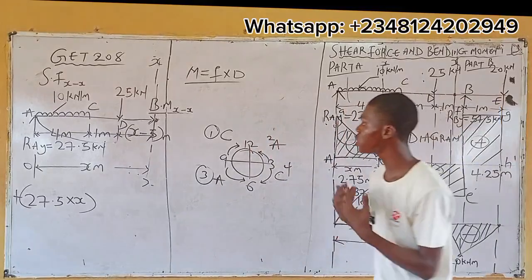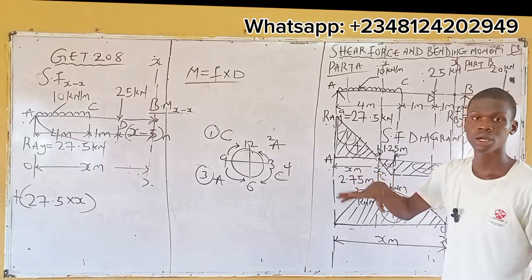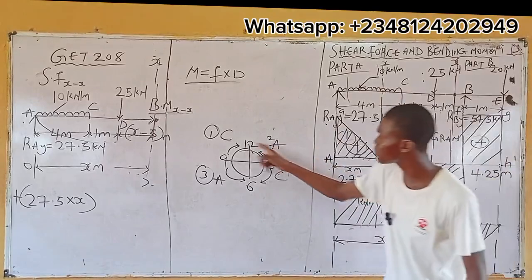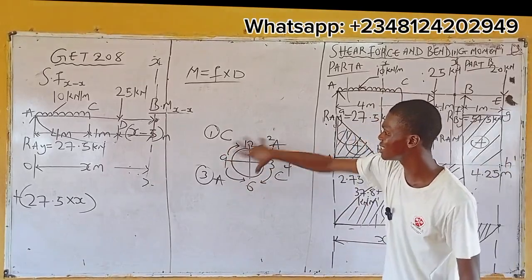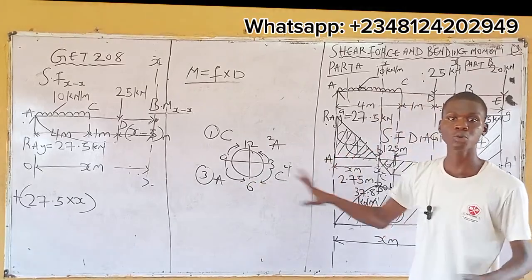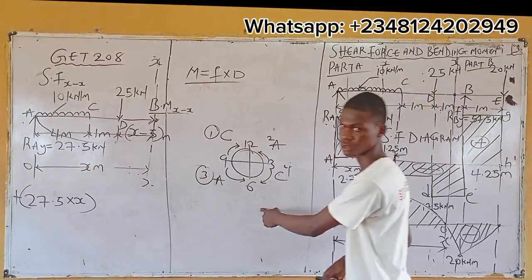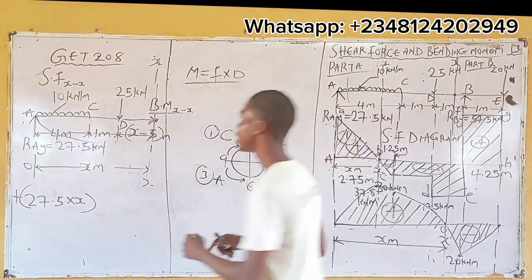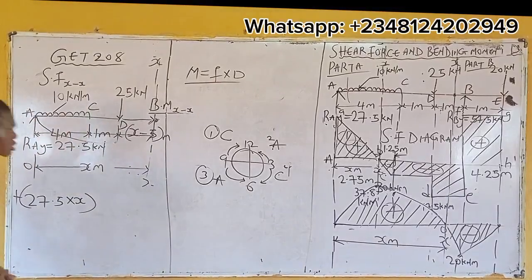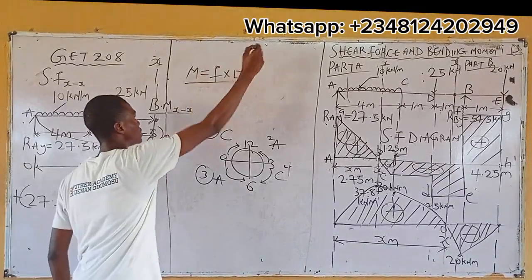First thing first, what I always do if I want to solve shear force and bending moment diagram, even in the last exam, is draw this particular beam and assign these directions: clockwise, anti-clockwise, anti-clockwise, and clockwise. With that, if I'm taking moment, I'll be able to check the direction. Are you getting me? Now, this UDL, is it going in a clockwise or anti-clockwise direction? Anti-clockwise, so negative. All into bracket, you need the force and you need the distance.